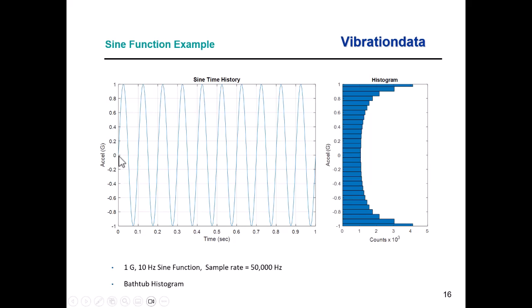So the positive slope zero crossing rate is where the signal goes through the 0 point there, and we just count the number of occurrences and divide by duration, and that's the positive slope zero crossing rate. And when we get to more messy signals, that's better than just calculating the frequency as the number of peaks divided by time. Now let's take a look at this histogram.